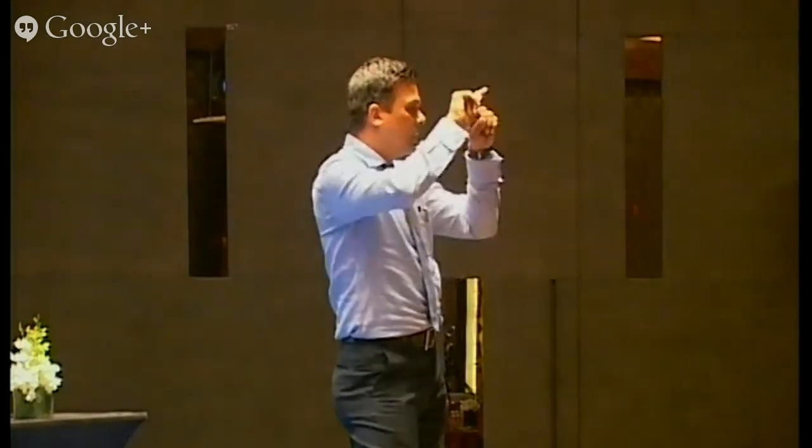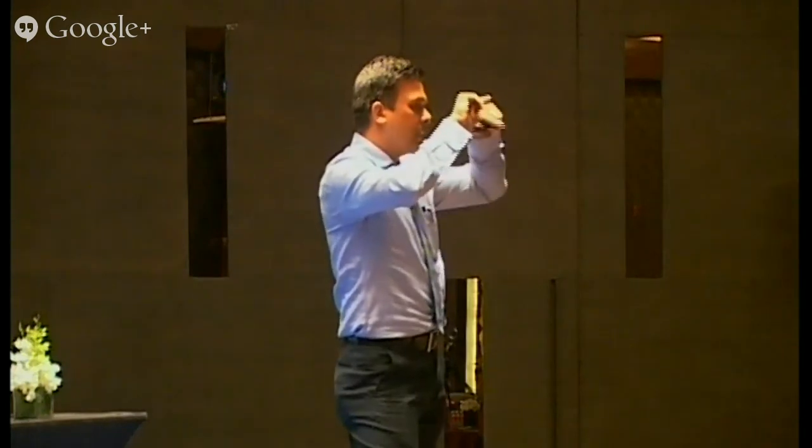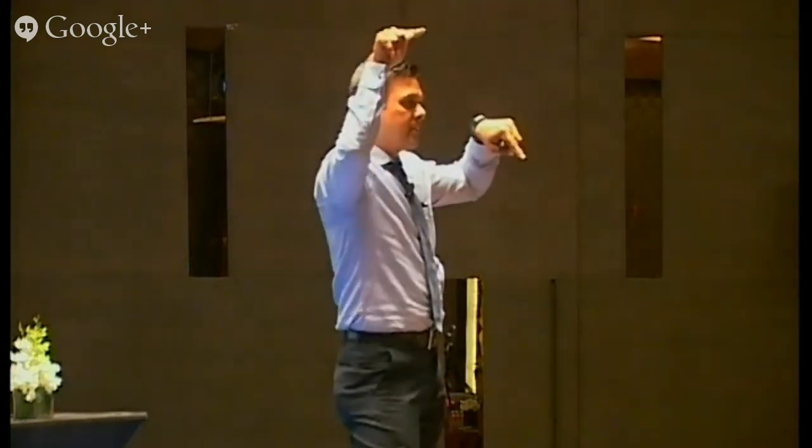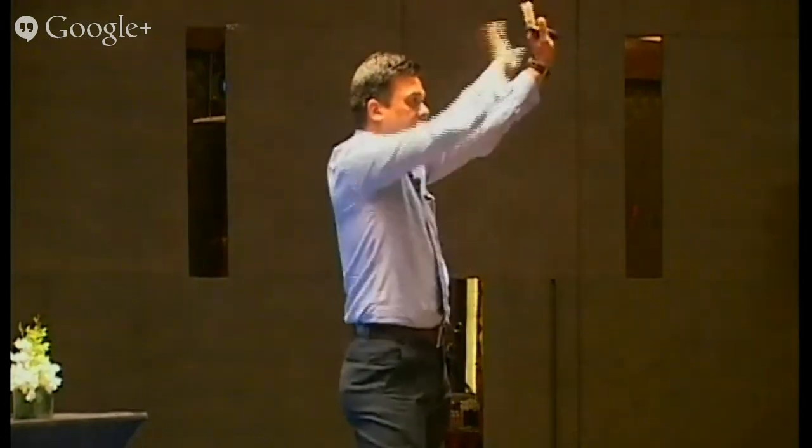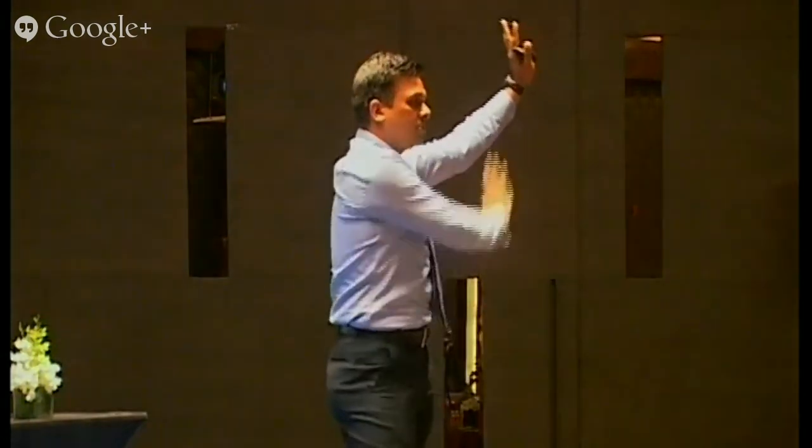You have the option to state the reference. You can, yes. So let's say you want to measure only this element with respect to this one. So then you make this as reference and then make this measurement. Normally how it is done, you make one element reference and keep on measuring with respect to each other. Not necessarily the edge element, it can be anywhere. It can be any element that you choose, because we want to calibrate the whole of the system.